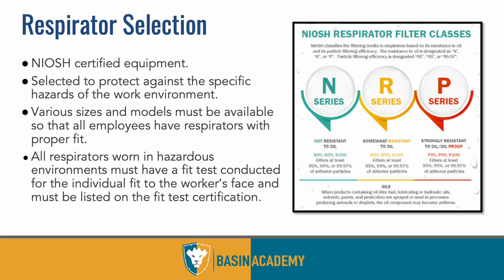Within that standard, though, depending on the contaminants you're working around, that will change what type of respirator you use, not to mention the type of cartridge you use. So you have to check the SDSs and then verify that with the marking on the respirator or the purchase documents of the respirator to make sure it's the right type for you.